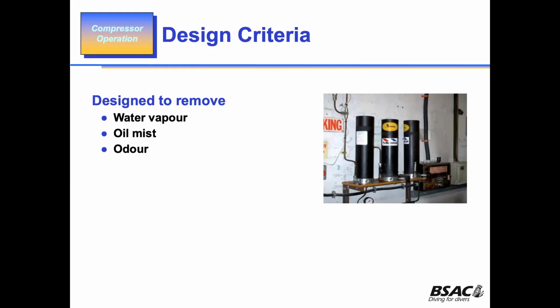Every time you pump that cylinder up, you make that cylinder warm, right? Then you go and jump in the cold water, you make that cylinder cold. So any moisture that's in there, if the air's not dry and completely treated the way it should be, will come out of solution.